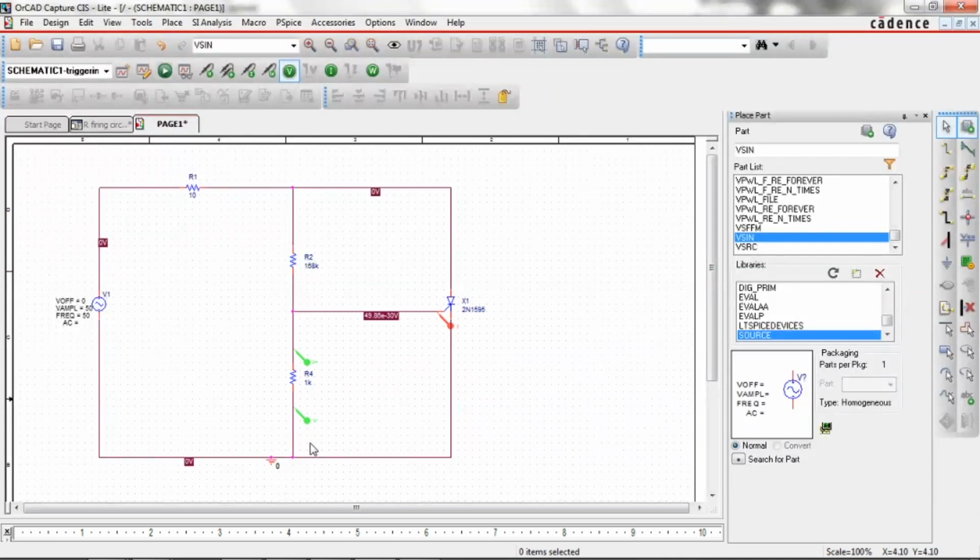So we are passing a current in this. Okay, as soon as this turns on, what happens to this current? See here, the current is coming here. This is turned on, meaning this is acting like a short. This is a low resistance path. The entire current moves this way, and no current moves this way until the SCR remains on. Then when the next negative half cycle begins, the SCR turns off once again, and the current starts flowing here. Until then, the current flowing here is zero.